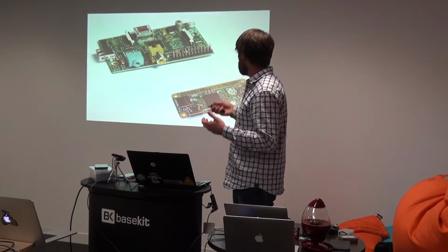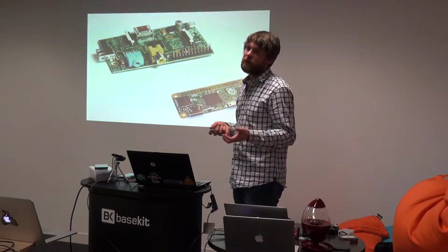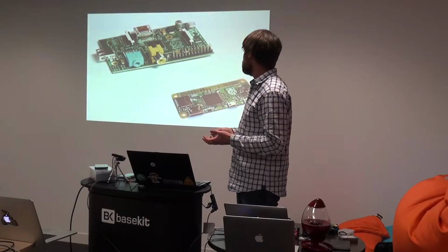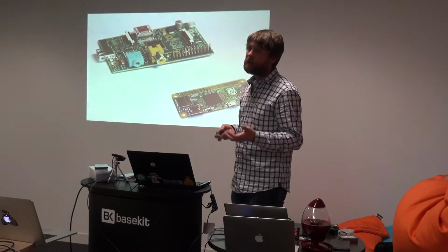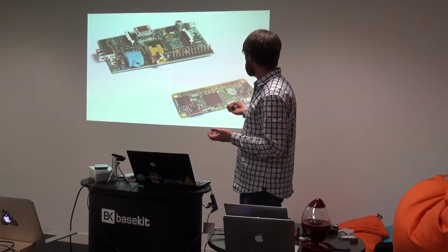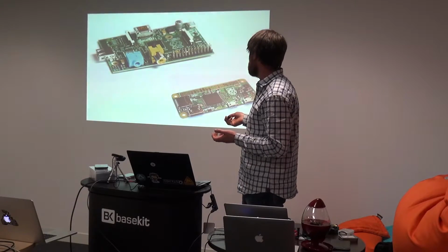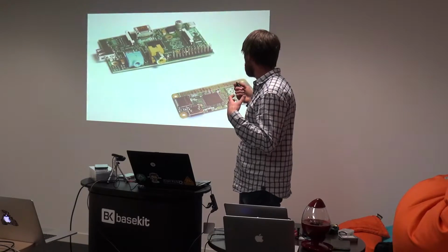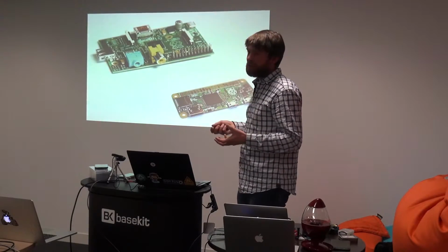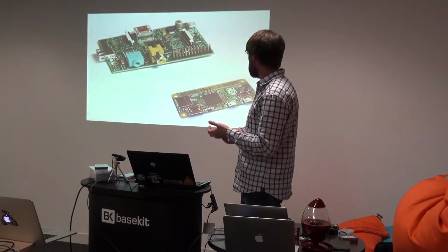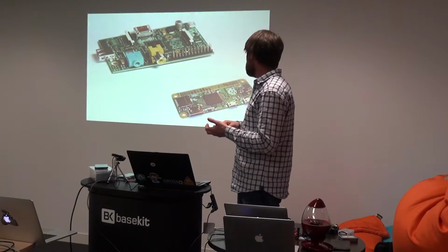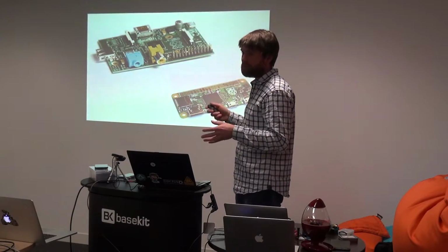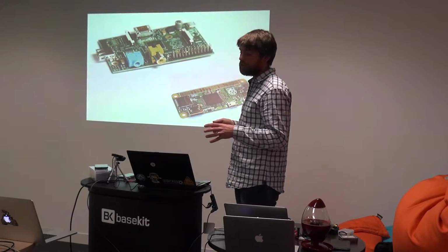So why wouldn't you do something like that with something like a Raspberry Pi? Well, the main reason really is power consumption. The Raspberry Pi Zero is by far the most power efficient one, and if you change some settings and specifically power off the output and the power LED, you can get it down to about 60 milliamps, which is pretty good going.